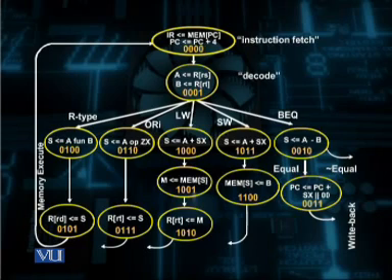During the instruction fetch state, as you know, two major operations are performed. The instruction code is read from the memory location identified by the program counter and transferred into the instruction register, and the program counter is incremented by 4 to point to the next instruction.